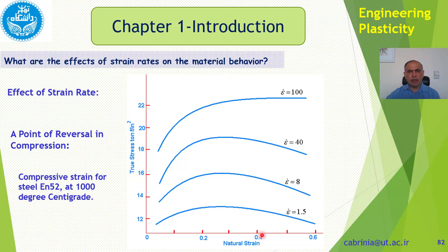harder on the material, or give the material more deformation, the strain increases. What happens is that I will show you later that as we deform a material, only 5% of the work we do goes to the deformation. 95% releases as heat. So as we have more deformation, more heat is released, and we have this 1000 degrees